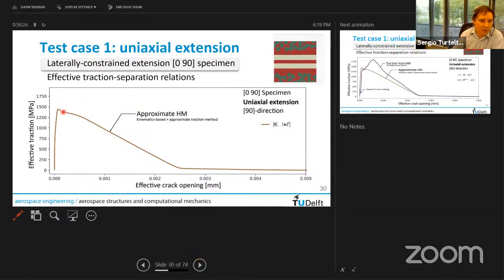And as you can see, the values around here are what you would expect from looking at the volume occupied by the fibers divided by the volume occupied by this section here. Yeah, so you don't get 5 gigapascals, but you get, in fact, a scaled version of that, because you don't just have fibers all over the place. You do have matrix in between.